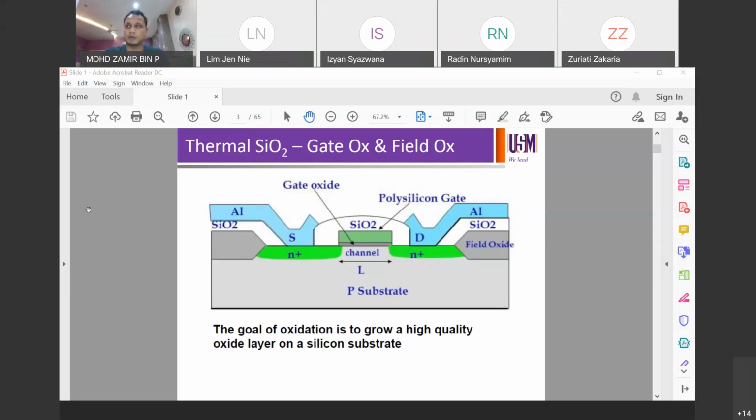And last time when we talk about MOSFET, we have discussed about, if you can recall, high K dielectric, because of the technology node going smaller, and the thickness of the oxide, particularly gate ox, is also shrinking. And if you're working with a very thin layer of gate ox, we could be working with possibility of tunneling as well. So we don't want that to happen.